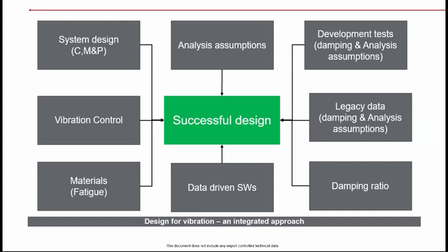That can actually give us the comparison, but that is again a cumbersome process because you have to take all the direction plots, and even sometimes the cross axis responses also we have to see. It's not necessary that the in-axis response will always be predominant. So for the mode shape to be commented on, whether the mode shape is properly matching or not, all three directions, all the accelerometers, everything should be properly overlaid, and then you can make a comment about the mode shape match. So to avoid all that, it's best to come to modal assurance criterion, or the modal analysis wise, and then just check the mode shapes based on that.